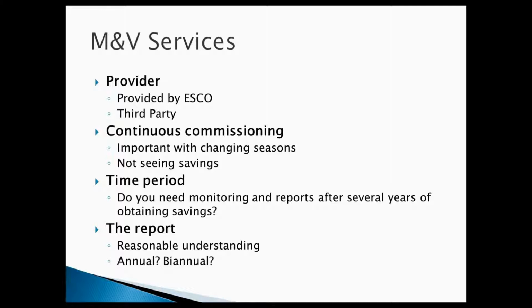Once we know what we're looking at, we also need to nail down that baseline. This is also another issue where we need enough information, but we don't want to spend too much money gathering it. Certain basics like hours of operation, fuel or power consumption, heating degree days, etc., are probably easy to obtain, where there are cases where individual measurements of load on specific pieces of equipment can be difficult and expensive to obtain.